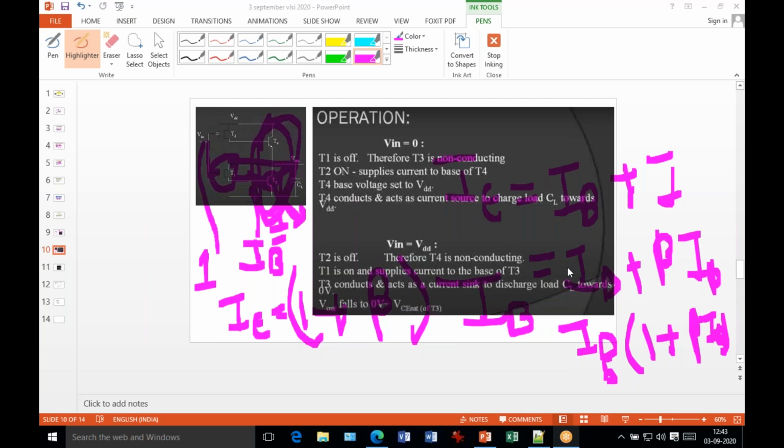Okay, that is one case that is understood. This is a disadvantage of bipolar technology. The complexity of the circuit is high because here the number of transistors is four: two transistors for CMOS and two transistors for bipolar, like NPN or PNP.